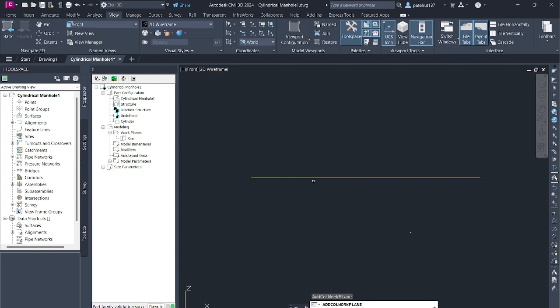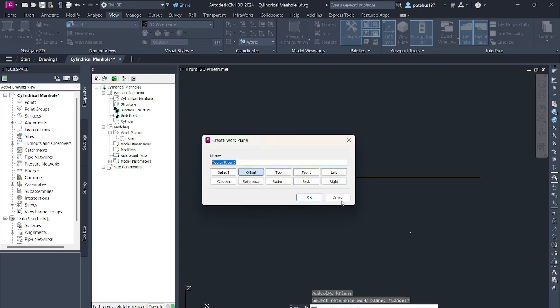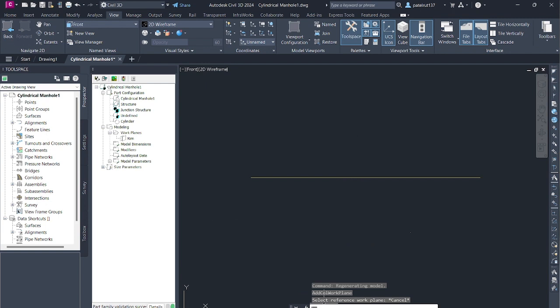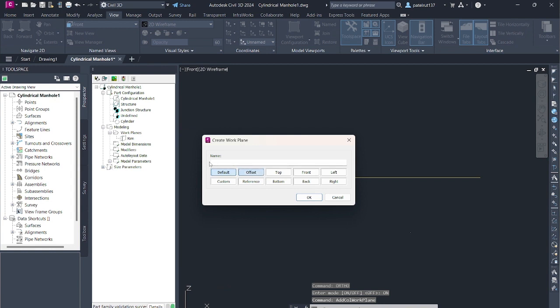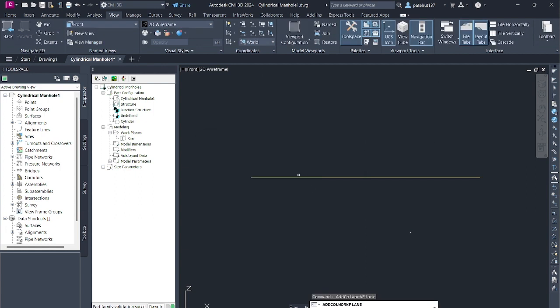These constants can be changed later to variables, lists, ranges, or tables for further part customization. Keep the Model Parameters dialog box open for the next step. Next, you'll change each of the work plane offset parameters, WP of 1 through WP of 5, to correspond with a structure parameter. For example, instead of the first offset being approximately 12 inch, it now corresponds with the SFH parameter. So if you later adjust the SFH parameter, the work plane offset, and its plane geometry, profiles and dimensions, will adjust accordingly. Select WP of 1, and then select Calculator.